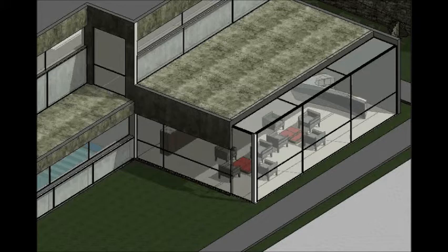A sunroom or a sun space is an isolated gain system. It can either be an attached greenhouse-like structure to the south facade, or it could be a part of a space without any interruptions in the plan. For this project, the space that is extruded outwards towards the south is partially used for the purpose as a sunroom, even though the system is used as a small portion compared to the size of the room, but yet it was quite efficient.